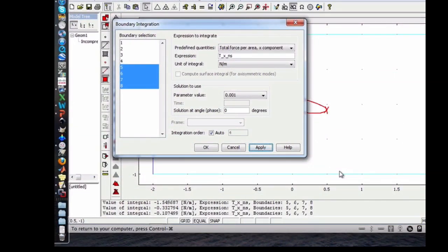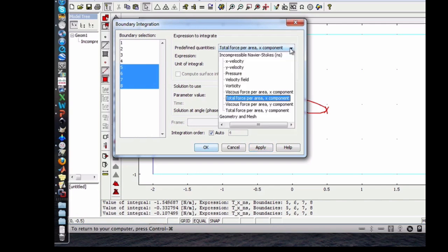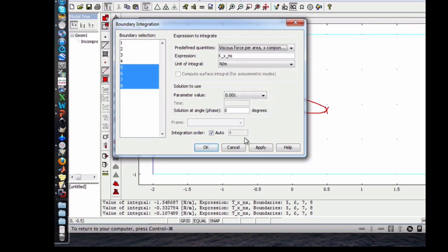So the other thing this allows us to do is show what the viscous forces per area would be. This is just the viscous component. If we looked at the very lowest Reynolds number, the highest viscosity, that force should be pretty close to the magnitude we got from the total drag, which was about 1,300 newtons. So it's close to that. It's about 1,000, so maybe 70% of the drag is due to that.